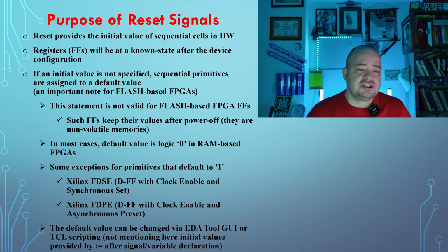So those initial values are not applicable for flash-based FPGAs because they behave like non-volatile memories and keep their last value before the power off, as I mentioned. But of course, if you force a reconfiguration from scratch after power on, then they will get those bit stream values again.